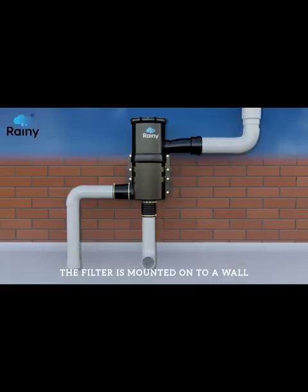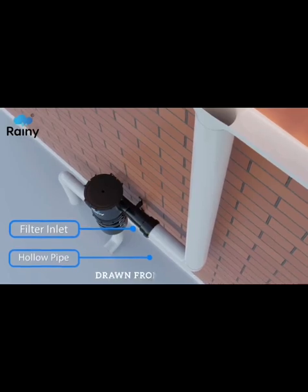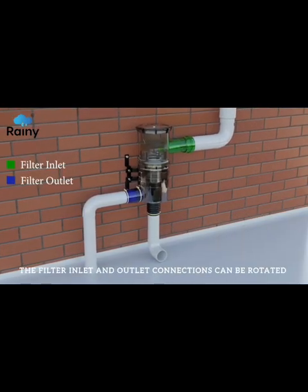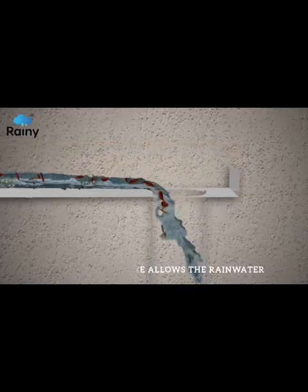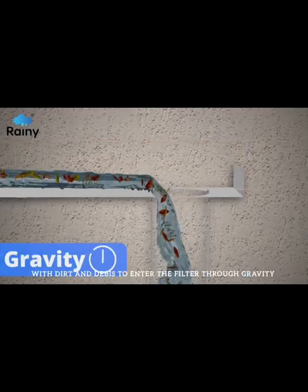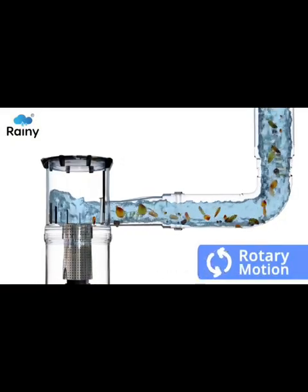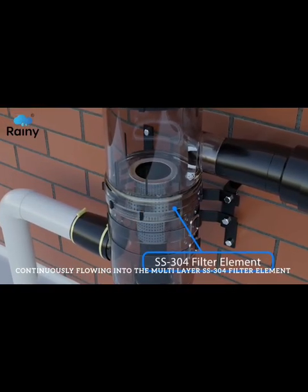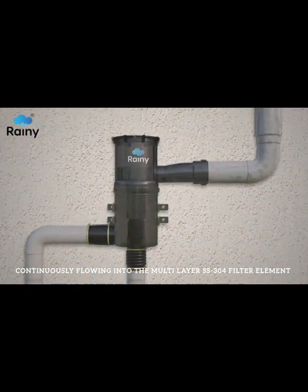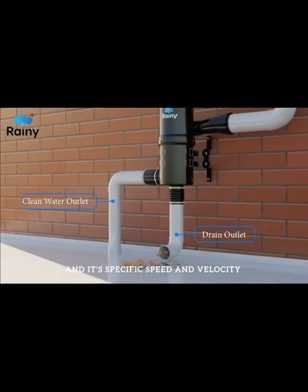The filter is mounted onto a wall and the inlet of the filter is connected with a hollow pipe drawn from the roof. The filter inlet and outlet connections can be rotated 360 degrees to suit the site conditions. The hollow pipeline allows the rainwater with dirt and debris to enter the filter through gravity. The rainwater starts to rotate in a retrograde motion at the periphery of the upper housing, continuously flowing into the multi-layer SS304 filter element, placed in the lower housing, at an angular motion and at specific speed and velocity.